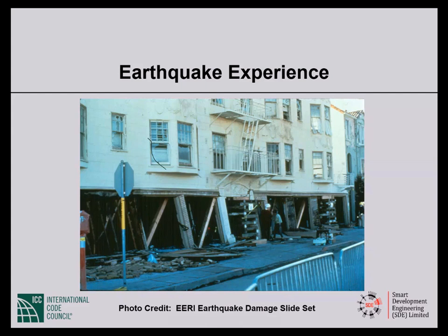And that resulted in soft stories. The ground story now had much smaller stiffness than the upper stories. And as a result, one building after another in the Marina district had serious problems.